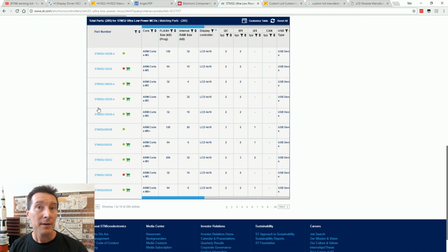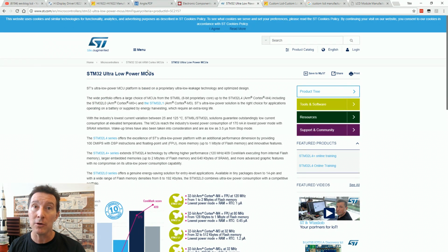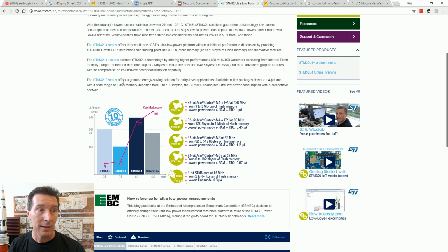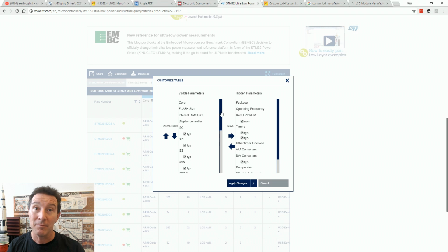columns that we needed. Now, if we go over here and have a look at, say, the ARM STM32 ultra-low power MCU line, which we happen to be using, and also use in the 121GW multimeter as well. We chose a particular variant with the built-in LCD controller that had enough pins. And what I've done here is I've sorted the parametric table. You'll hear this term a lot, parametric table, and if you don't know what that is, it just means having all these different parameters, hence why it's called parametric table, of the chip.